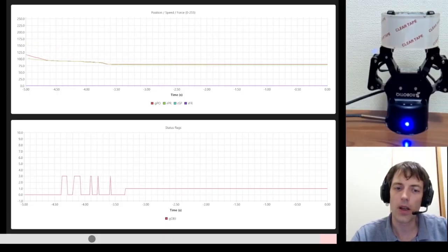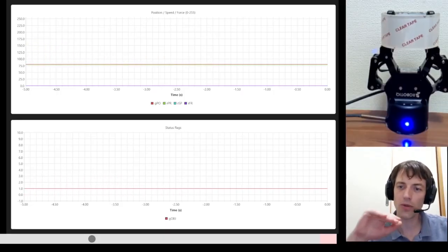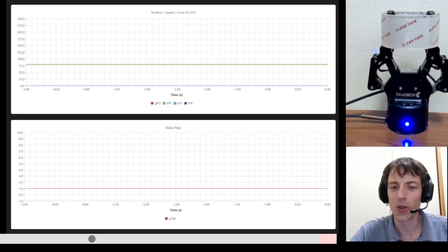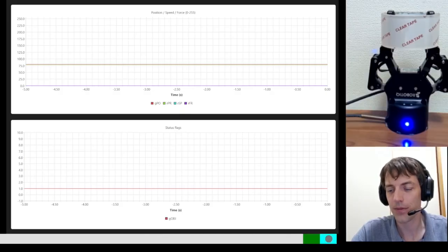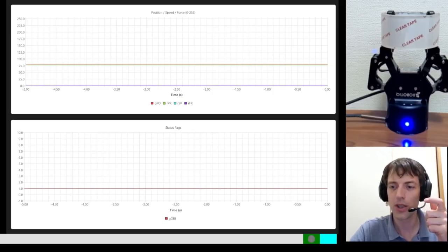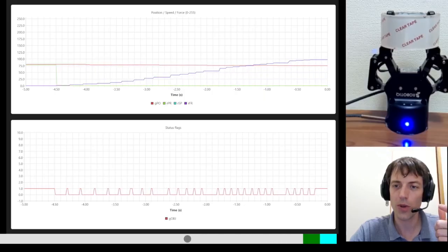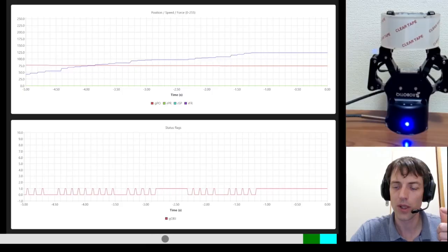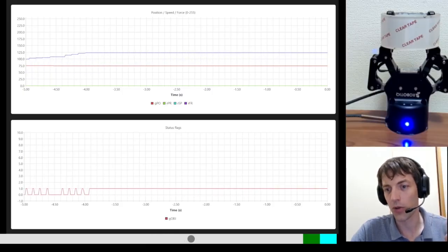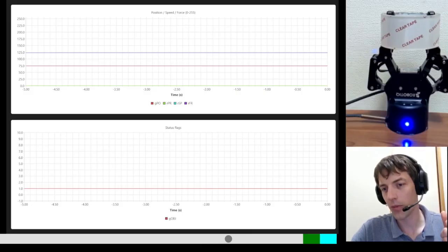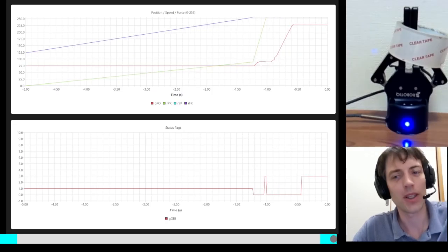But this time, to enter the force control mode, you have to go the other way of the control range of the joystick. So here it means that you will need to press the trigger completely to enter into the force control mode, and then you release the trigger, and the more you release the trigger, the more grip force you will have. And to exit the force control mode, you press the trigger, release a little bit, and repress the trigger, and then you get a release.